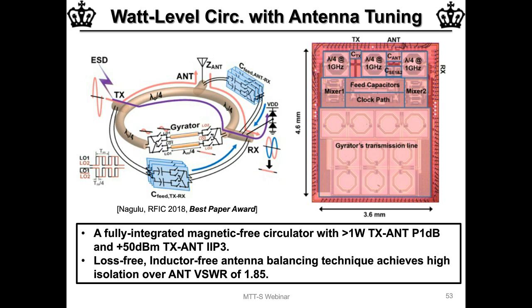Okay, and then along the same lines, there's a question here about what the noise penalty is for using the active devices. Can you comment on the noise as well? Yeah, that's a good question. One thing I would clarify is that these are not active devices. These are passive transistor switches, meaning they have no bias current. Of course, there's a clock signal that is driving them, but they are passive switches.